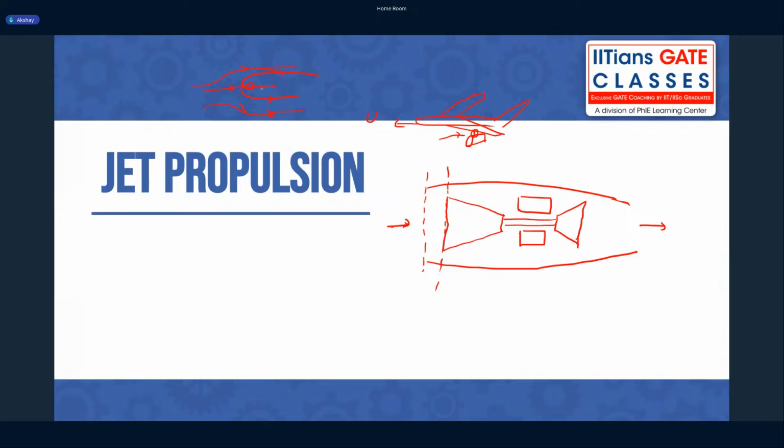But from there, if you find out the distance between this stagnation point and this source location, you can always find this ratio, the maximum height, how much it can reach. So S by D, let us take. How much should this S by D be, so that I can have a uniform flow that doesn't feel the disturbance, right? That is the whole idea. I don't want a flow coming at this location to be disturbed when it reaches the engine. That is a very important concept. So I want to make sure this S by D is such that the disturbance is kept below a certain level. Okay, yeah. That is the discussion for another day.